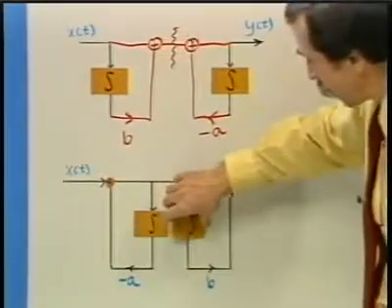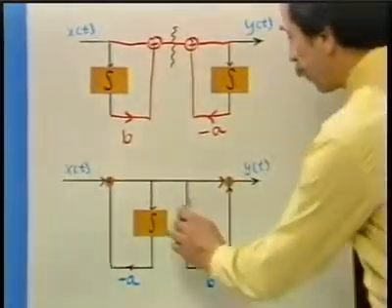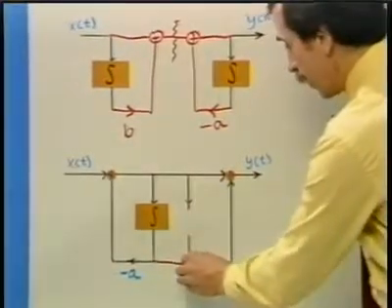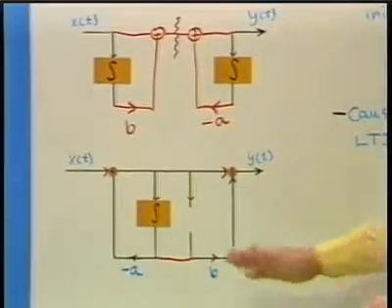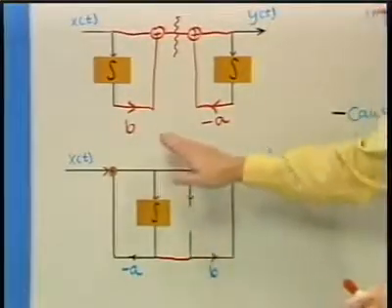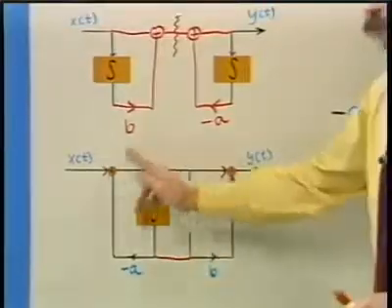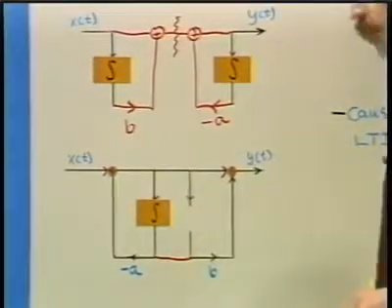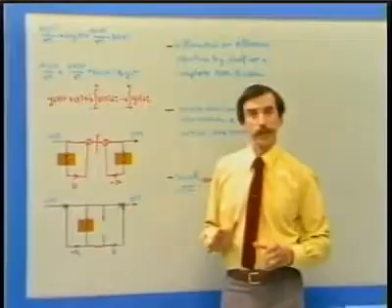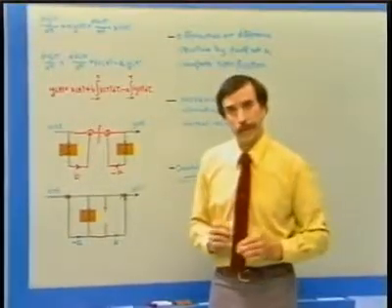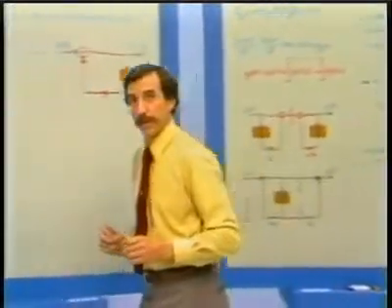We can remove this integrator, break this connection, and tap in at this point. And so what we've done, by interchanging the order in which the systems are cascaded, is reduce the implementation to an implementation with a single integrator, very much similar to what we talked about in the case of the difference equation.